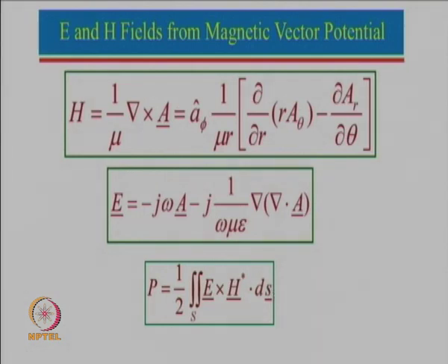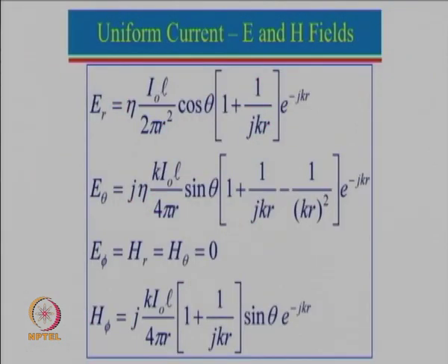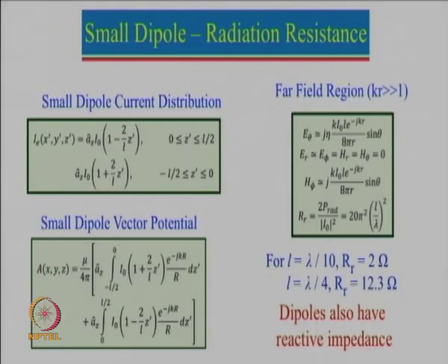Now, what is this R r? I just want to mention here that R r is nothing but a radiation resistance. It is not a physical quantity at all. From antenna point of view, power radiated is a fantastic thing. It is radiating in the free space, that means the antenna is radiating. But from circuit point of view, the radiated power is actually a power lost.